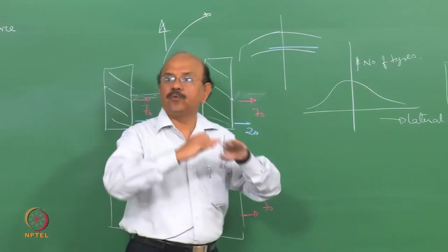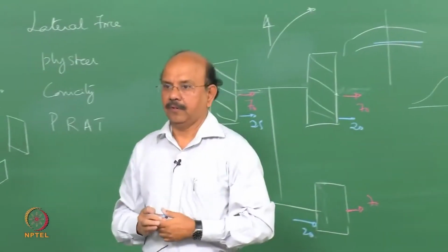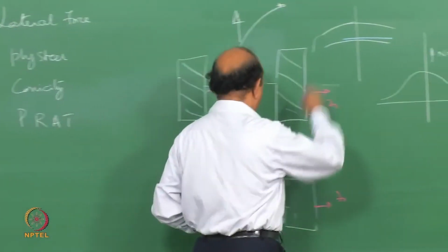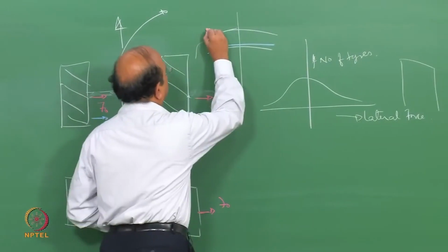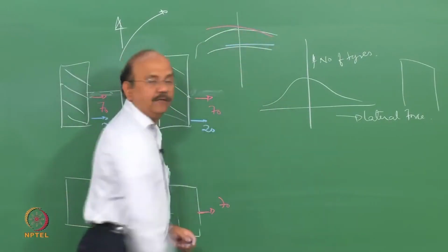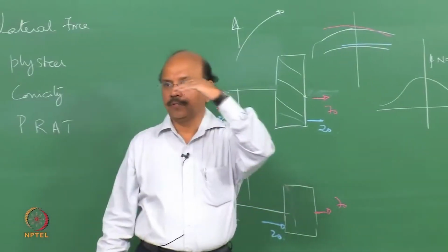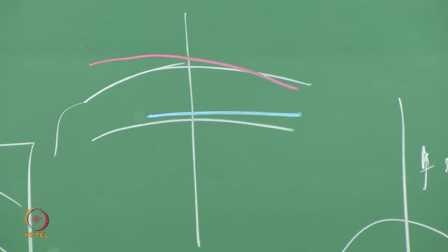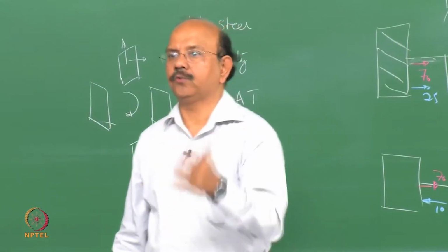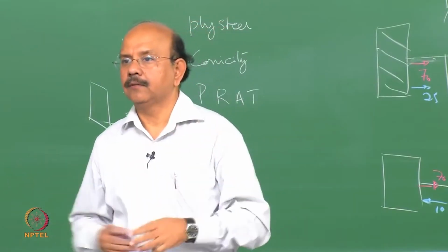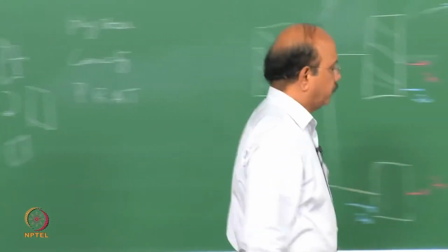So it would not get a nice symmetric shape, and the shape of the tire after inflation would look something like that, in fact. So the crown of the tire is not going to be symmetric, but would incline. So when this tire is rolled, you produce what is called the conicity.